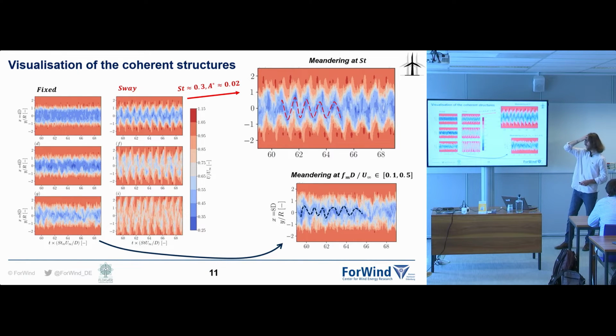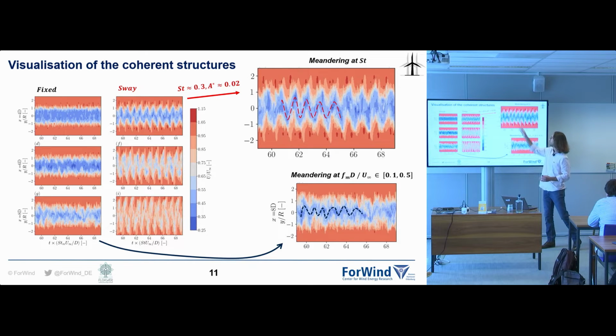We do believe that this has two effects. First, it will enable a higher transport of momentum into the wake. That's why we have more energy available, this recovery parameter. And also, it redistributes the energy more. So you will have regions where the wind speed is high and it goes in. So it's a double effect: higher transport of momentum and, let's say, wake redistribution.